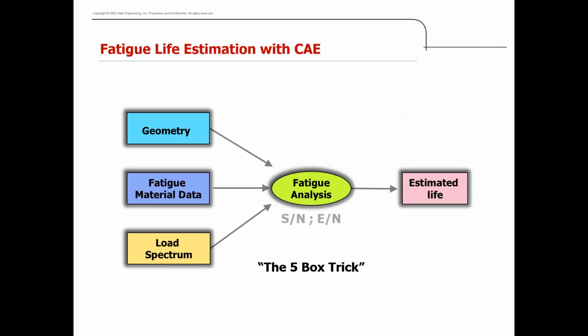So just a brief picture of how the loads generation applies, since we're talking about durability in this section. The load results, the bottom box, is the key piece that comes from the analysis that we're talking about today, the multibody dynamics analysis. In addition, you pass in material data or results of understanding how stress per unit load is generated on a component, and together that can go into a tool that does fatigue prediction.